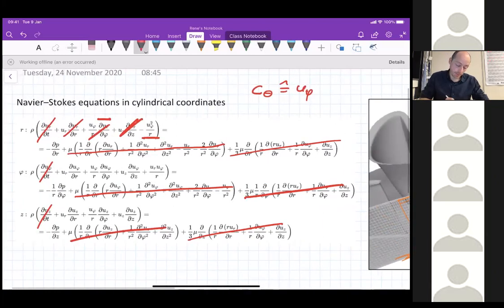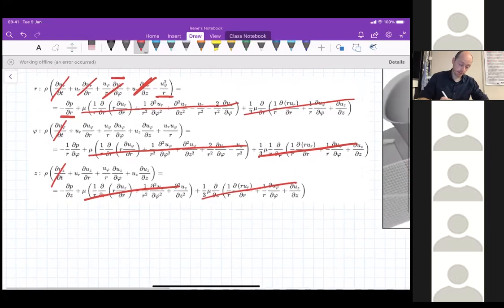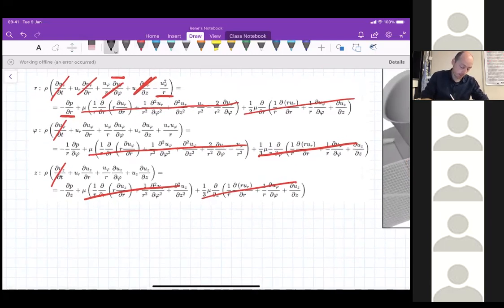And so C theta squared divided by r is balanced by the pressure gradient, dP dr, which means that I need to have a pressure change in radial direction, right? And this is simple. You could have seen it already and guessed it probably, that the pressure gradient dP dr, and there's a rho here, not to forget this rho, so I can put 1 over rho, is U phi, and let's write it in our terms here, C theta squared divided by r.